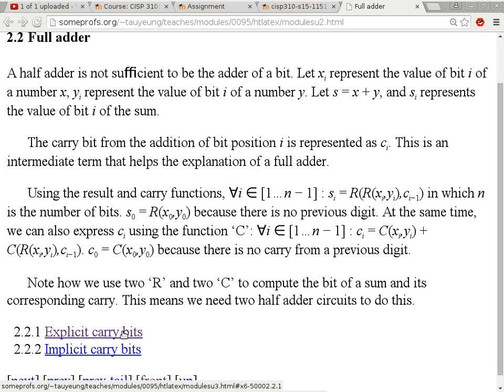Yeah, that's actually how they grade chips. In the past, I don't know whether they still do it or not, you can buy chips that are rated at 2 gigahertz. Some are rated at 2.2 gigahertz, some at 2.4 gigahertz, and so on. They may all come from exactly the same die. It's just that when they go through the characterization process, some work reliably at a certain frequency, and some will work at a lower frequency. It's still reliable, but it cannot go all the way up to, let's say, 2.4 gigahertz.